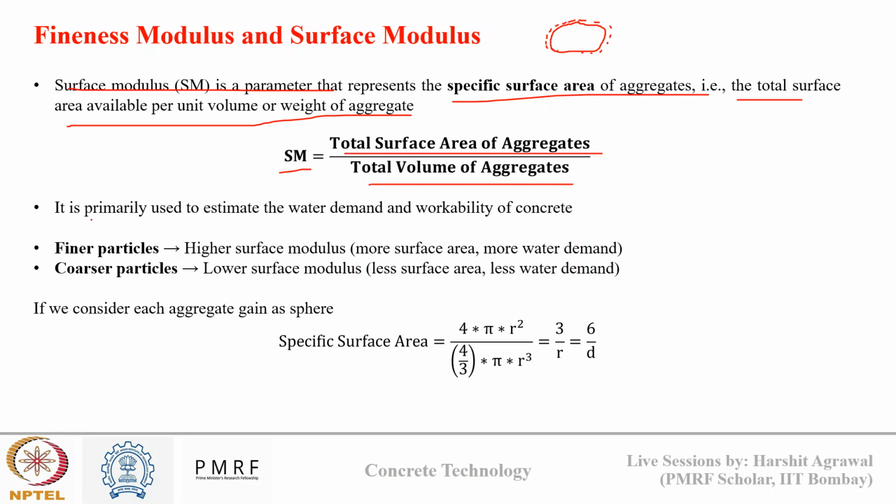And why is it important? It is primarily used to estimate the water demand and workability of concrete. We know aggregate does not contribute to the hydration reaction. However, if my aggregate is dry, it will absorb some water from the concrete.